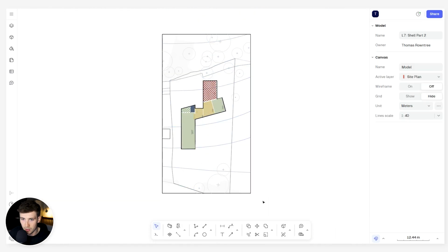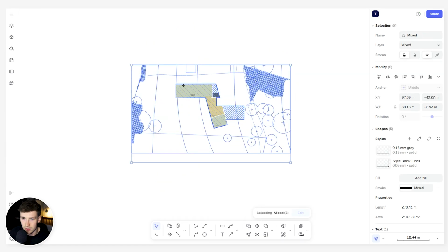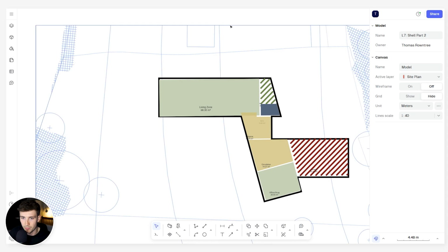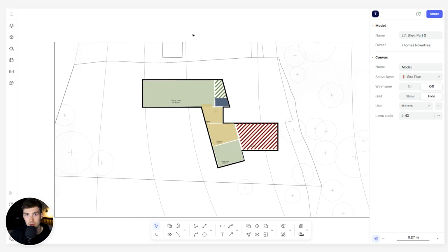And then the final thing I'm going to do is rotate this 90 degrees so that we have this back wall parallel to our sheet. Now, the reason why I'm rotating this is because when you're drawing floor plans, you ideally want everything to be either perpendicular or parallel to the sheet. Therefore, it makes it a lot easier to offset walls, to create much more accurate drawings that have straight lines. It's the worst thing, having wonky lines everywhere. It's really difficult to work with.